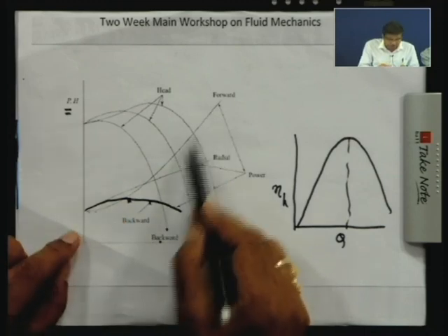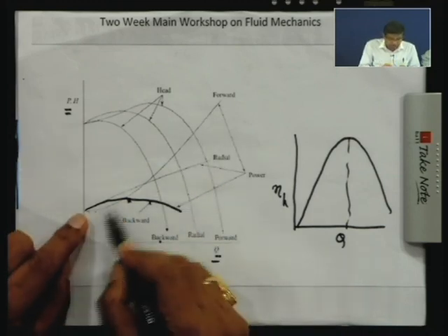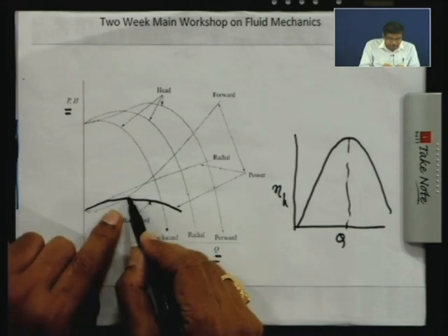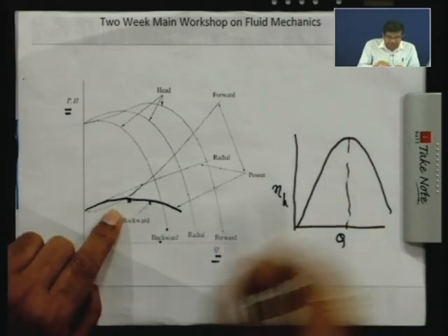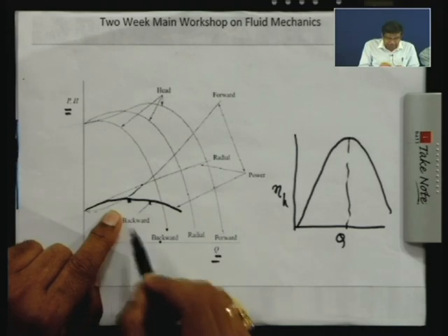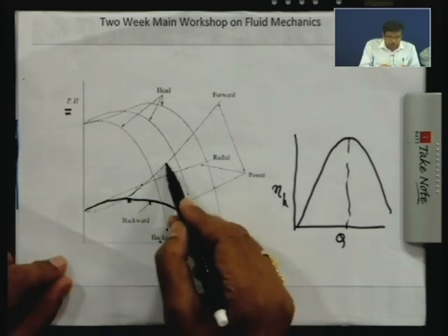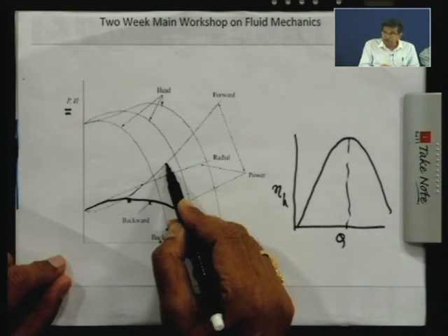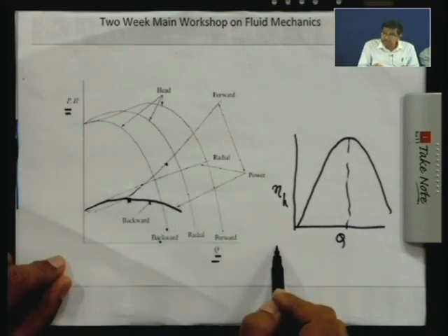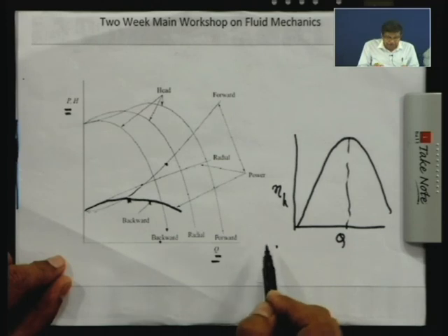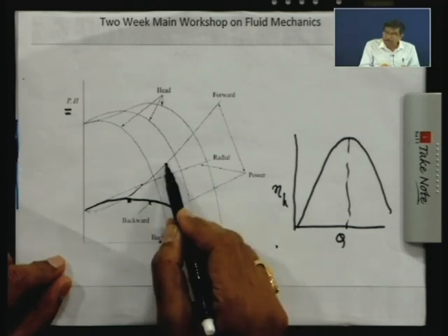But what happens to a forward facing vane? Let us understand. For a forward facing vane, you want to operate somewhere here which corresponds to the maximum efficiency. But by chance the flow rate is increased, it goes to an off design condition where power will be more. So, therefore, we have to rate the motor for some higher power.